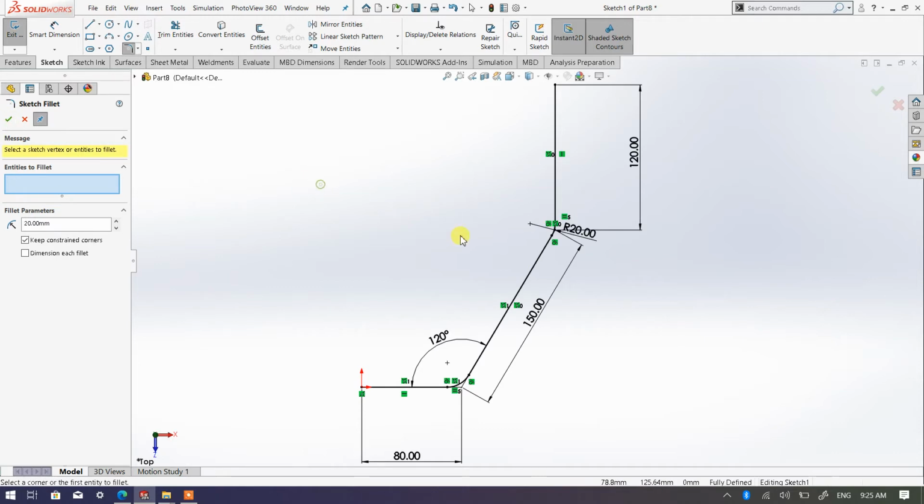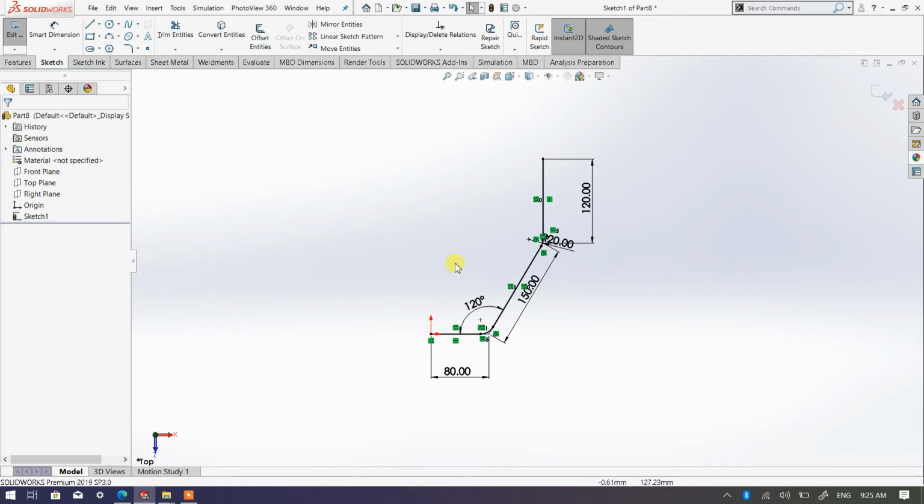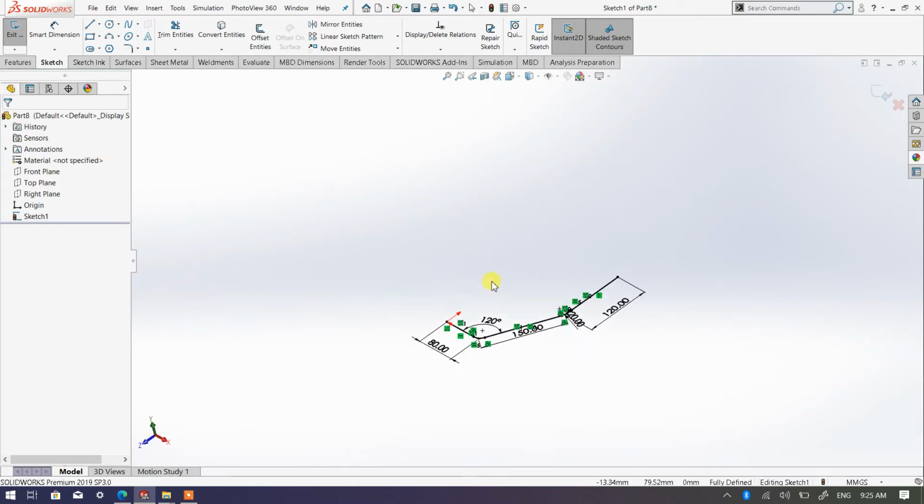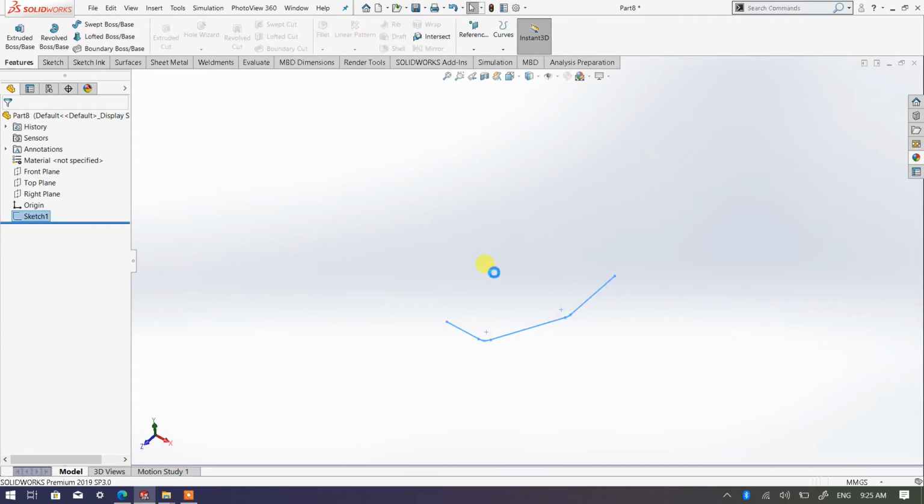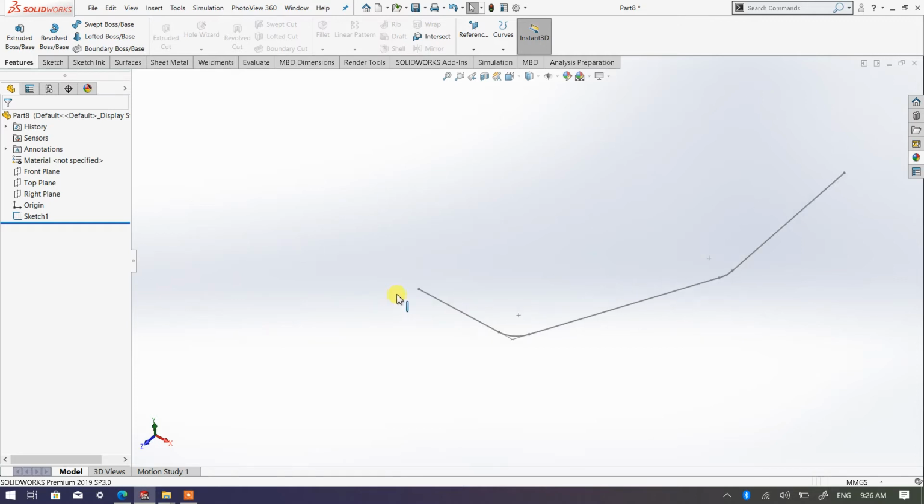And then this is my path. You still remember this is my path, right? This is my path, and I'm going to exit from my sketch. Now, I'm going to create my profile. If you still remember from our previous video, I've already told you that our profile should be perpendicular to our path here at this beginning section over here. It should be perpendicular, right? The profile together with this path, right?